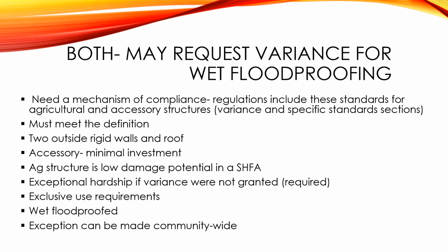topographic, your hydrologic and hydraulic situation. So having your technical data demonstrating the low impact to public safety and welfare, that kind of thing, include data on your flooding conditions, the kind of duration, frequency, depth, warning time, and safety and access that you have.